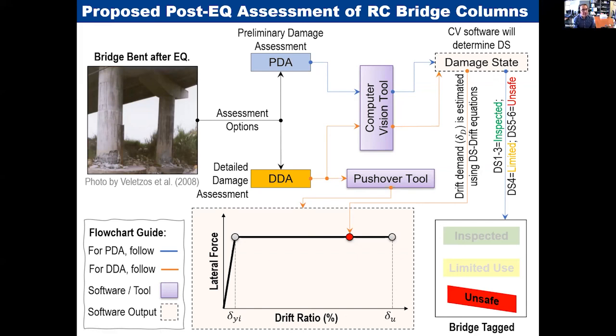We did 2 checks. One was the database. So you have 300 columns, then you do a statistical analysis, that's your accuracy. And the single column that I actually showed you, the 6 damage states, and they worked fairly well. Might be a case that is slightly off, but we try to have a conservative equation. You want to have a safe bridge within a few hours, and then after 2-3 days, trained personnel can get there and they can comment on that. You want your local folks to comment on the bridge fast and quick.